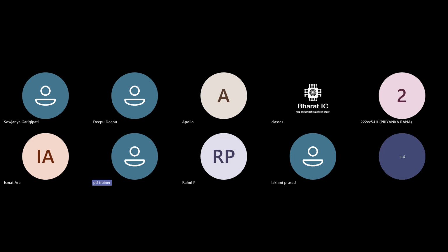If they are having more connections with the standard cells, then we have to tilt the macro or flip the macro and make sure. Is tilting acceptable, ma'am? Rotation only we can do, like by 90, 180. That we might not be able to do now, but flipping we can.